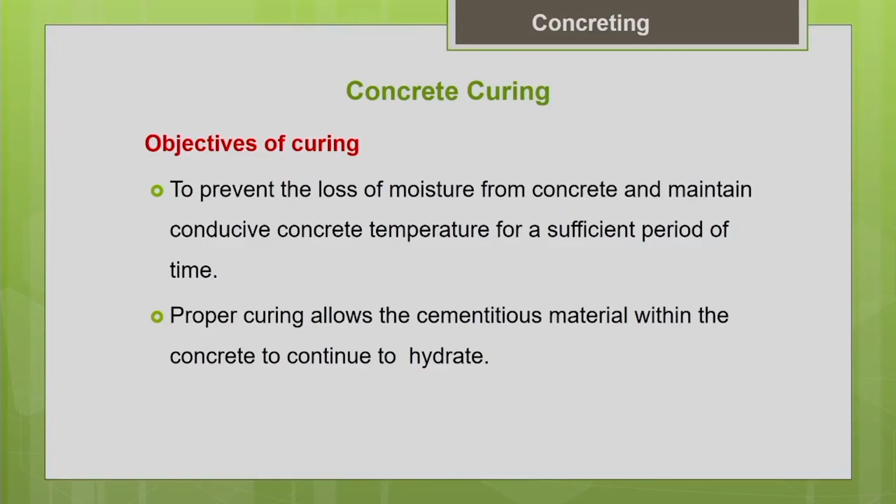So it is very important to facilitate the hydration process to be continued for a longer time. Then only you can get your desired microstructure, strength and durability of your concrete. Basically, whatever water you have added for preparing the concrete is itself sufficient for the hydration process. In most cases, the water we have designed for concrete making is sufficient. But when the concrete is exposed to the ambient condition, the water from within the concrete will be lost to the outside environment.